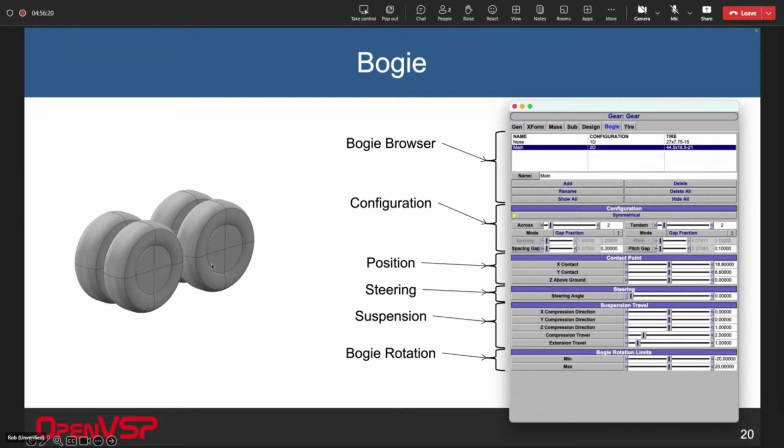And if you weren't aware, there's an FAA designation, a standard, where a 2-2 is actually represented as a 2 duplex. So the configuration up here, I actually write that. I write a 2D. So there's a 2 duplex, or if you go to a triplex or a quad, this configuration represents that FAA designation. Then you can dial in the spacing between them, either side by side or longitudinally, whether you want to specify that as a gap or a dimensional distance between them.